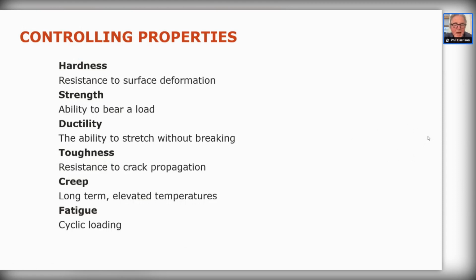Materials such as steels have defined yield points, called the upper and lower yield point in the majority of steels, which is easy to see on a tensile test. Other materials do not have this luxury, so we use what's called a proof stress. The proof stress is calculated from various factors, which is outside the range of what we're talking about now, used for the test piece.